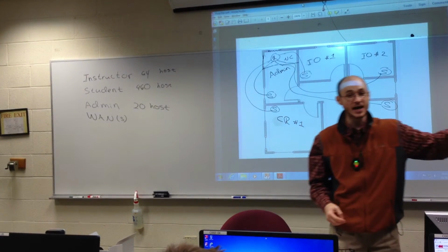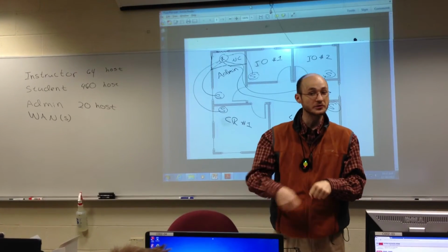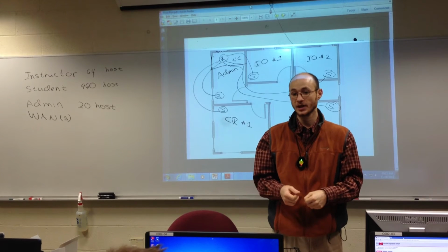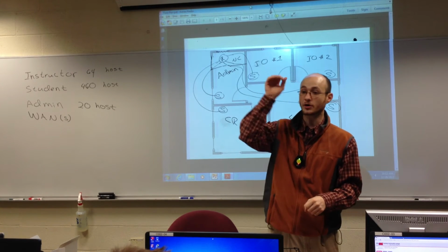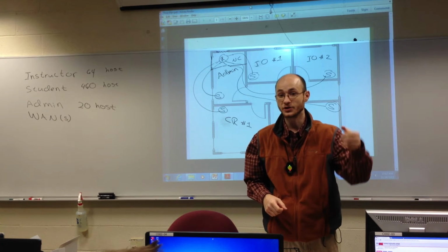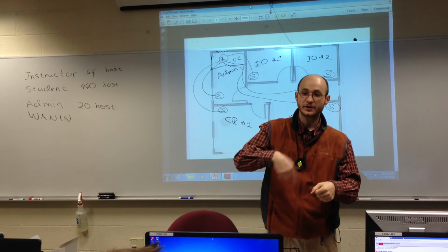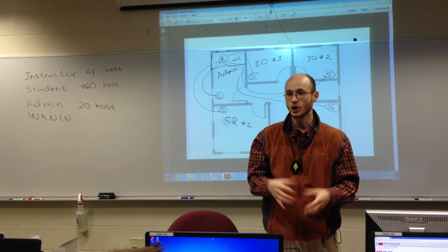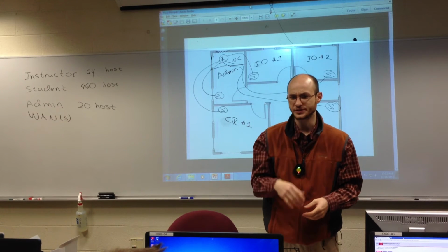Now, you take 5 cables, 1 out of each box, you take some electrical tape, and you bind them up. It is easier to run a bigger bundle than it is 1 cable, especially across ceiling tiles. You're pulling it at one time, and you're getting 5 cables. And every so many feet, keep tying some tape around. You want that bundle to be intact, especially when you're running long distances.